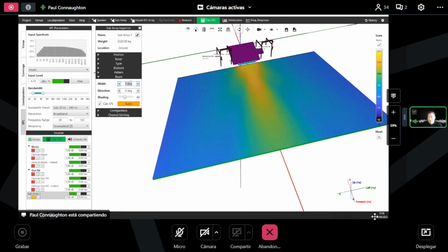As I said, beam width can be changed from 1 to 180 degrees. Please be aware, this is very important. I'm sure most of you are aware of this, but having extreme values such as 140, 160, I mean, asking an array to do 180 degrees worth of coverage is more than likely going to provide very unuseful results.